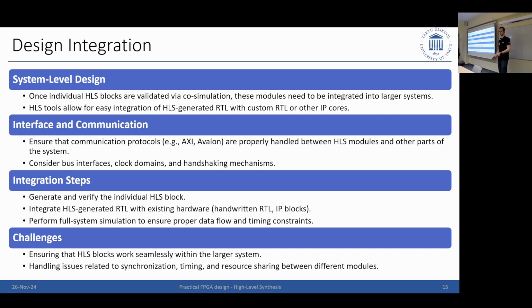So this is why you then need very huge test benches, because you can always do each of your design blocks separately, but these communication considerations, and the clock domain crossing, all that stuff, is what you gotta consider in the end, and you gotta verify that everything together works.